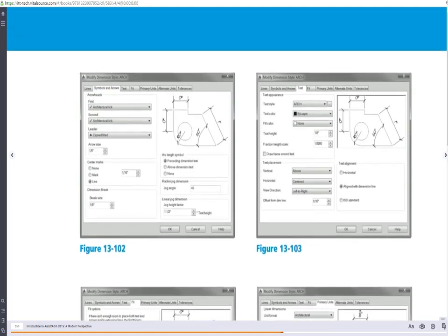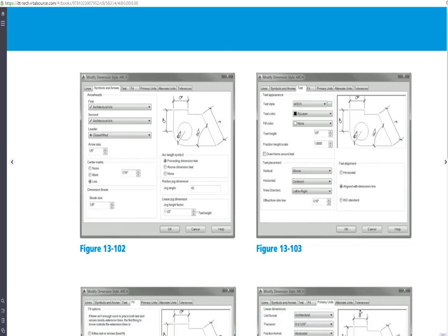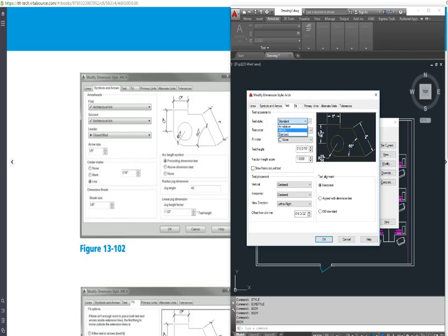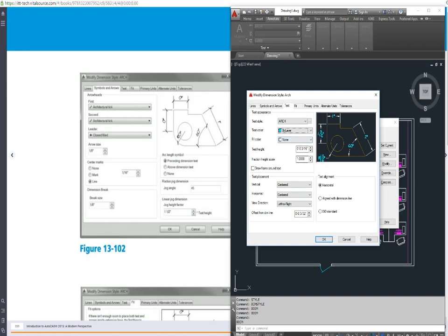Then come up here. We've got architectural, bilayer, none, above. Let's set those. That's on the text, so you'll see it on the text tab. I'm going to come over here, text. That's the architecture font we created right at the beginning, and we want it to be bilayer, and we want it to be an 1/8 inch above, centered, left to right. Above and centered, left and right, and a 1/16 of an inch.